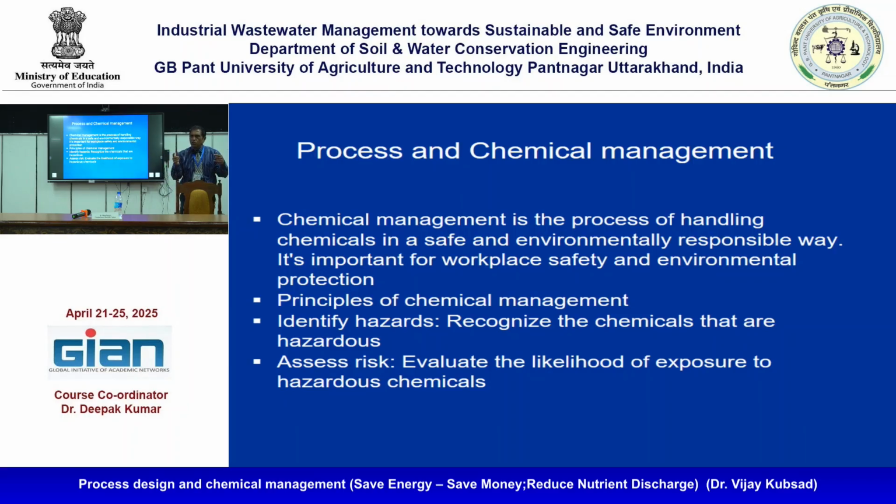But there is also another process. In the equalization tank, we took a low pH wastewater and a high pH wastewater and we neutralized them. Is it not smart? But there was an opportunity. If you tell the industrial dischargers, you treat and change your pH at the discharge, because it is a regulation, pH should be between this and this, then he will also treat.